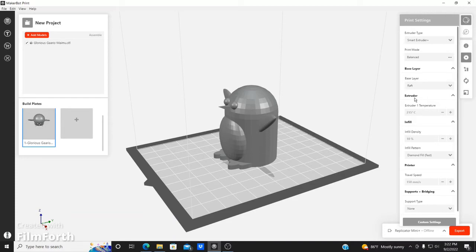Okay, extruder. On your temperature for the extruders on your filaments, there should be an indication or instructions on there that says this is the infill filament that you have. It'll say PLA, ABS, PETG, or other filament that you have, and it'll give you the temperature range between those two. There should be a point A range to point B range. For example, if you have a filament, your range is going to be about 195 Celsius up to 220 Celsius.